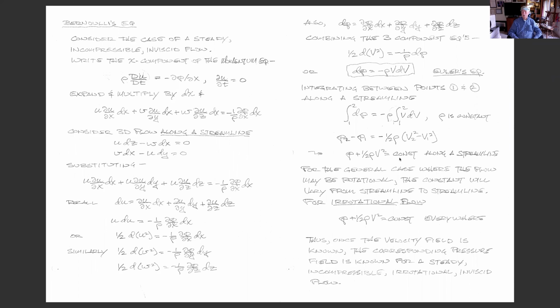Upstream, the flow is parallel and uniform, and so it will be on all the flow outside of the boundary layer for the flow over the body. That flow out there we call potential flow. And we are going to be able to solve problems with this. To get elegant about it, we can go to analytic function theory using complex variables, and all the math works faster than the way we're going to do it.